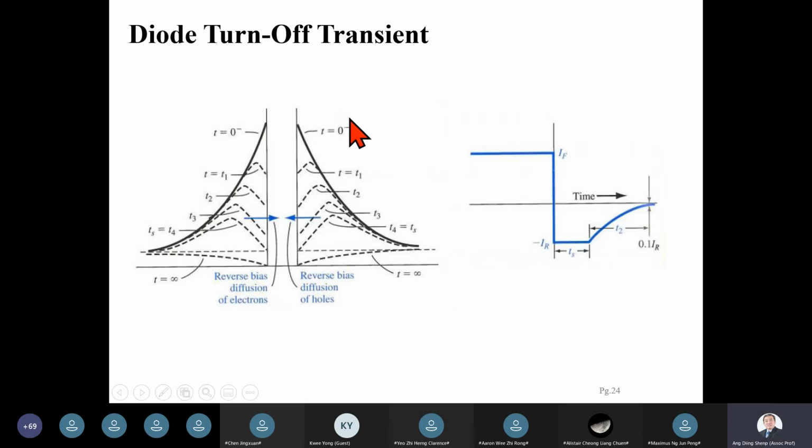So at the very time you toggle the switch, pretty much the same excess minority carrier charge is stored on both sides of the junction. In other words, even if you toggle the switch from left to right, you can think of the diode as remaining forward bias, but the direction of the current can change.